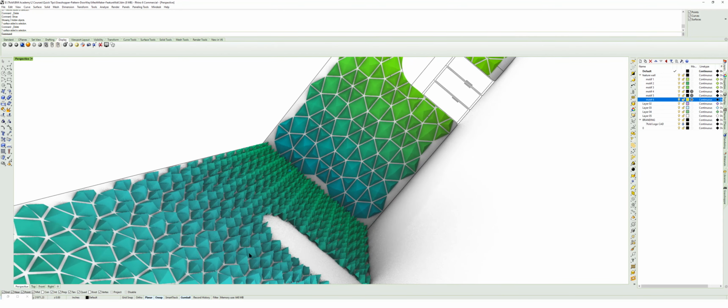I want to go ahead and flatten that down by right-clicking, hit flatten, right-click, flatten. And then I want to create a set. So type create set. Merge those in by holding shift. And then that's going to give me the unique values that are in that set. So 82 and 15. Now I just want to make sure that my shortest direction is always on the top.